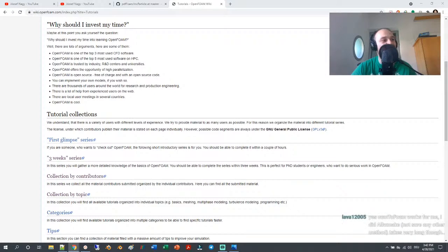As an industrial guy, I would say to make sure that your Y+ is not 5,000 or 20,000, but is in a region which is reasonable. If you have something with 100 or 200 in certain regions where you're not interested, then I'd say it's fine. And if it is too low, then you don't need the wall functions.